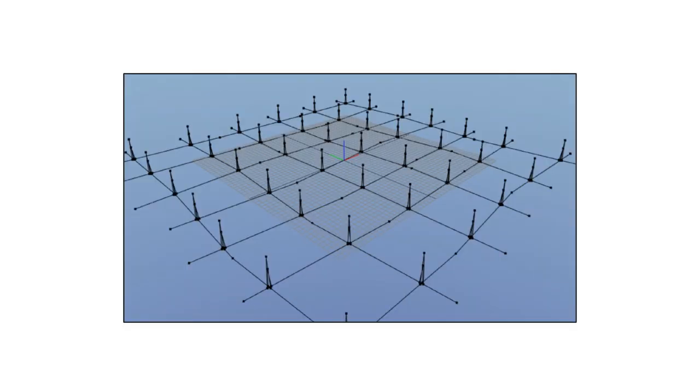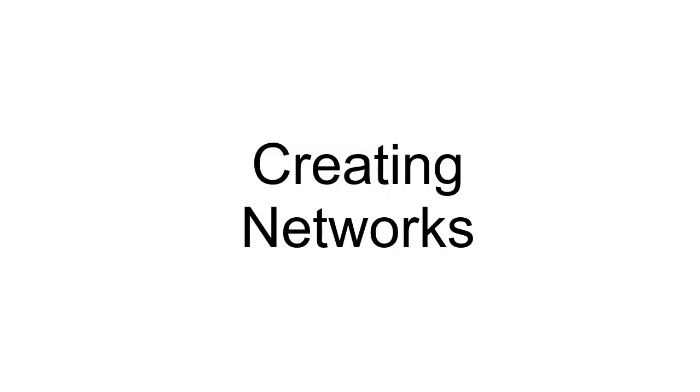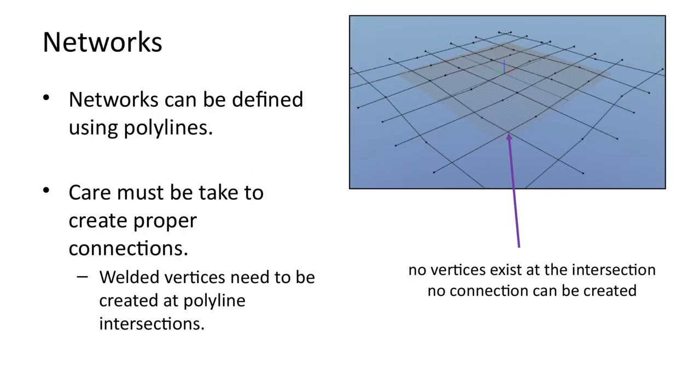In this video, we will look at creating networks from polylines in Möbius Modeller. Networks can be defined using multiple polylines. However, care must be taken to create proper connections between different polyline edges. A connection requires polyline vertices to be welded.